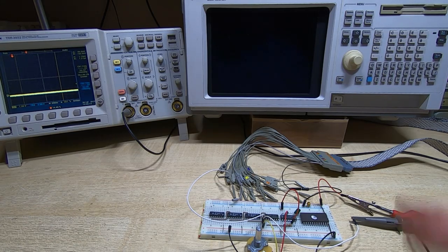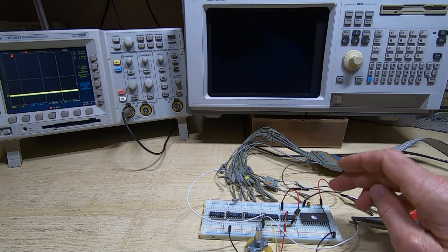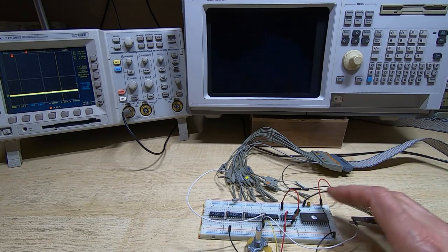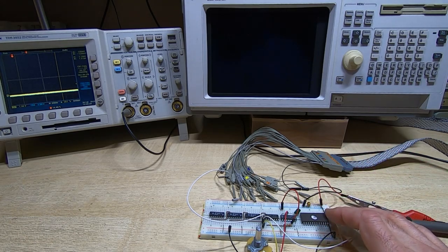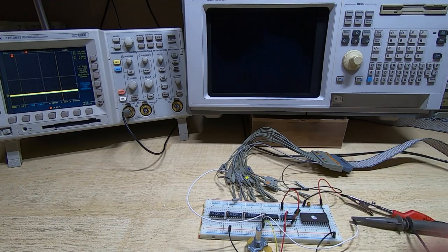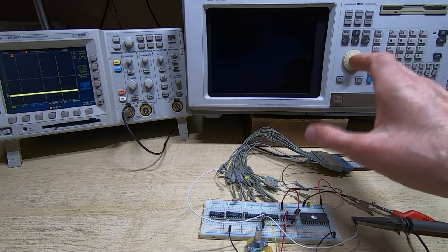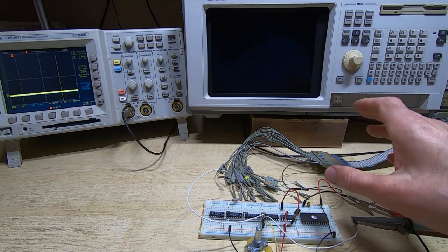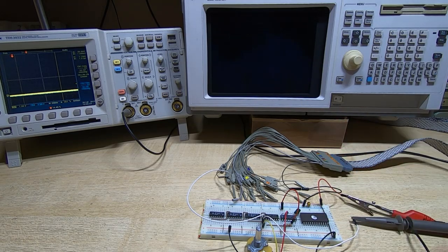So for this one, the first thing I want to look at is the signal level that you feed into the analyzer. Most of the time they're hooked to something like a TTL system, so the standard default levels work fine. But if you're developing a system or you're using an FPGA or something like that, then you may well need to change the levels.